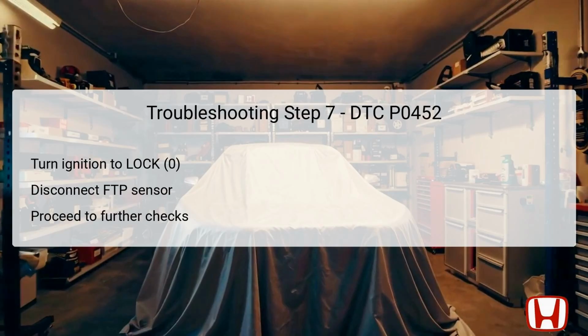Lastly, once the sensor is disconnected, you are set to proceed to the upcoming steps that will help in diagnosing whether the sensor itself is the root cause of the issue or if the problem lies deeper in the vehicle's electronic systems. For Step 8, the technician will turn the ignition switch back to on 2, allowing the systems to